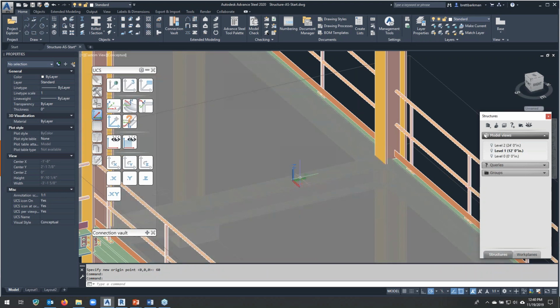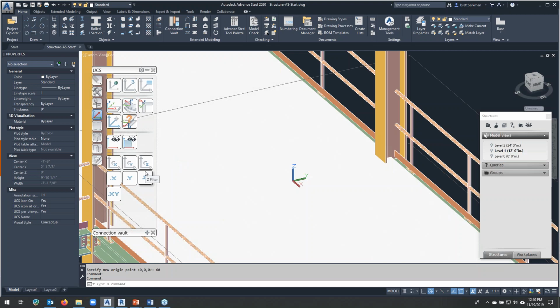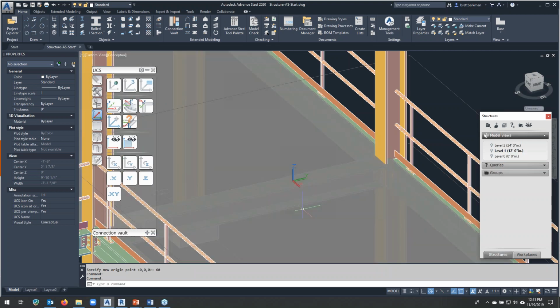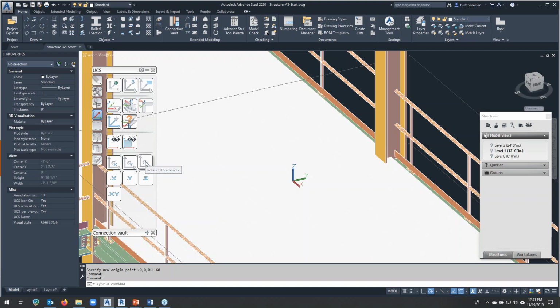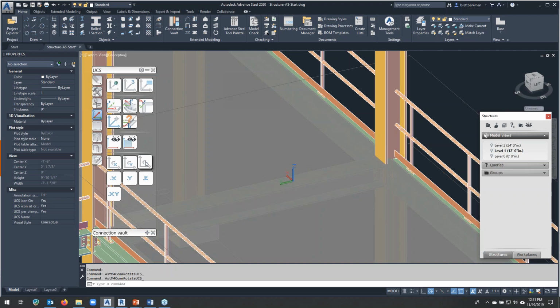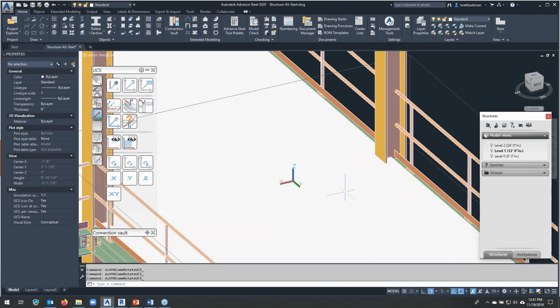The next thing you want to do is orient the y-axis to a certain direction. With cage ladders, they like the y-axis to be walking in the same direction as you would as you approach that ladder. So what you'll find yourself doing is rotating around Z until Y is pointing in that approach direction for that ladder. In this case, it will be in this direction here. So all you do is just keep clicking your rotate button, depending on the axis that you want to rotate around until you see what you want on the gizmo.